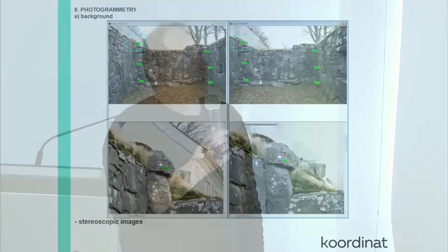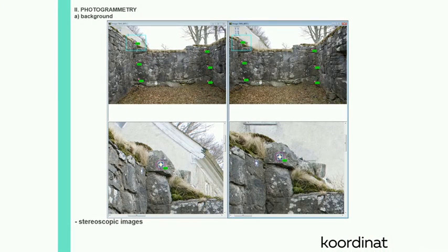So I will start, of course, from the older sister of laser scanning, which is photogrammetry. I am using, until now, stereoscopic photogrammetry. I am using single picture photogrammetry in certain cases. I will show them later on. The point is that in the stereoscopic environment I have better control on the area of interest, and I have a much better possibility to calculate precisely what I want to achieve, basically the level of detail.